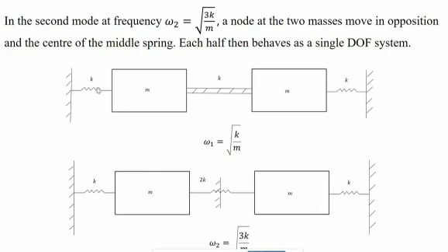Say it is delta 1, and the displacement in the second spring, K2, may be delta 2, and then the total extension will be delta 1 plus delta 2. But if that takes place under a force P, a pair of P we are applying from both the sides, then that P is common. P is acting in both K1 and K2.